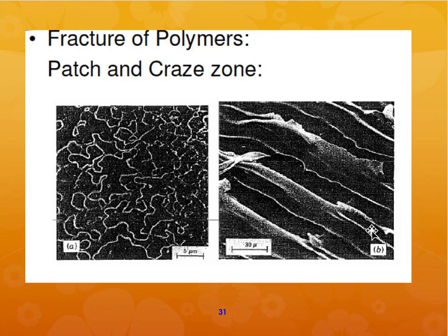it is called crazing. For example, if it is polycarbonate and you are using it for your lens, you can clearly see through that lens, right? Because it is clear and flat. But suppose you have crazed it and you had created scratch marks in it. Those could be happening right here. So you can see that here. And you cannot see through this glassy type of a material or a polymer type of a material.